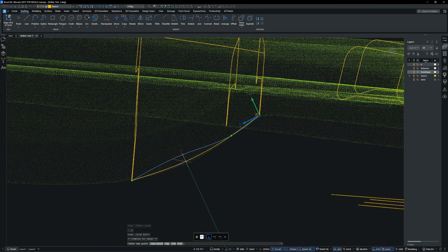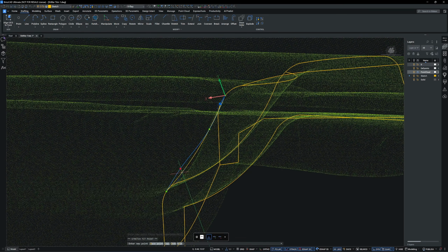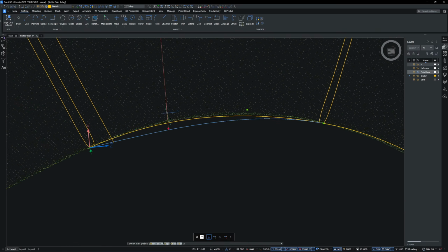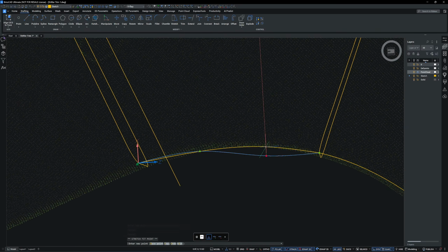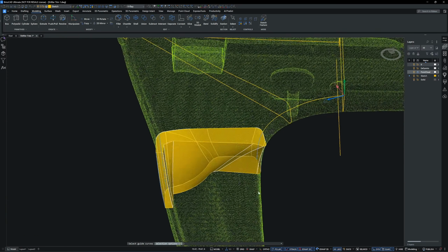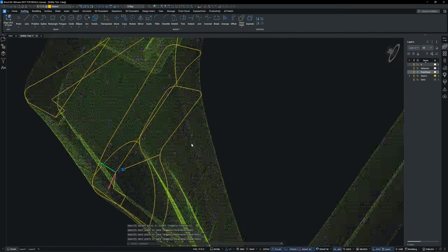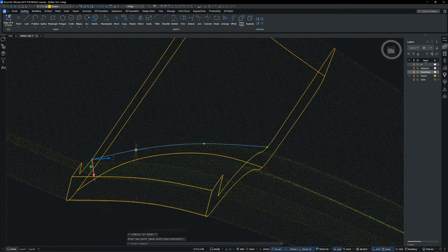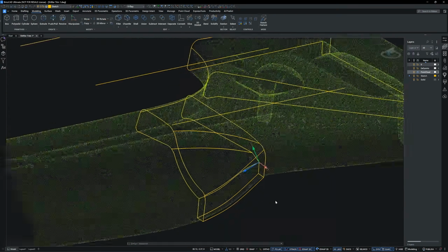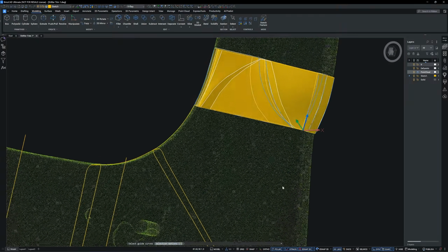This segment needs guide rails to force the shape, so I'm using splines for the rails. After creating them, I will experiment with the Loft command to see if more rails are needed. If more rails are needed, I will simply add them and run the Loft command again.